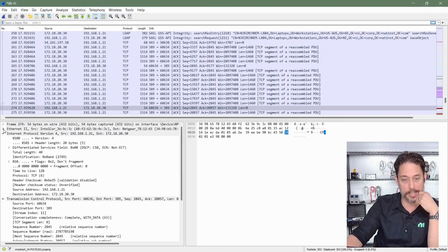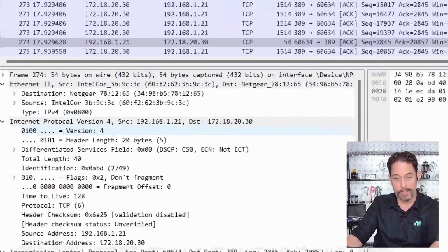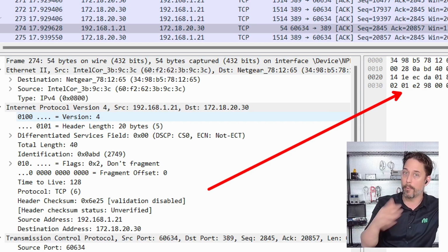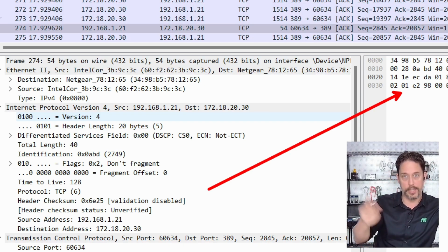So I can expand it here, and you can see all of the actual things that are loaded up into that binary blob. And this matters quite a bit, because one of the things I found out very quickly, even after connecting it to a COM port and doing a little bit of magic to sniff on the COM port, is it's just transferring binary information. But you're in luck. LabVIEW does a lot of favors for you when you're interacting with binary information.